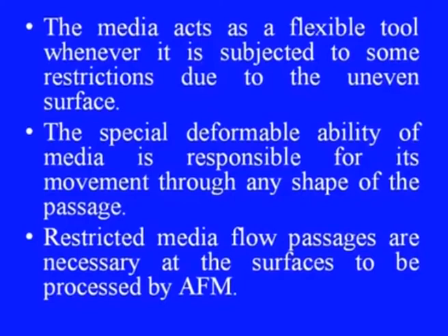It is extruded under the given pressure across the surface which is to be machined. The media acts as a flexible tool whenever it is subjected to some restrictions due to the uneven surface. The special deformable ability of this media is responsible for its movement through any shape of the passage.